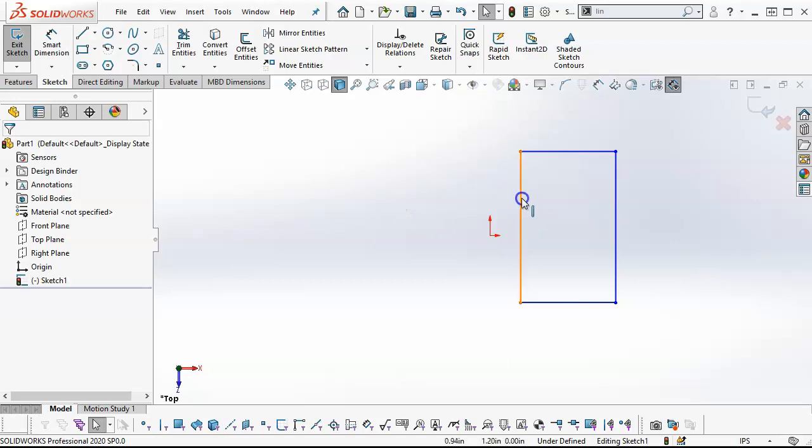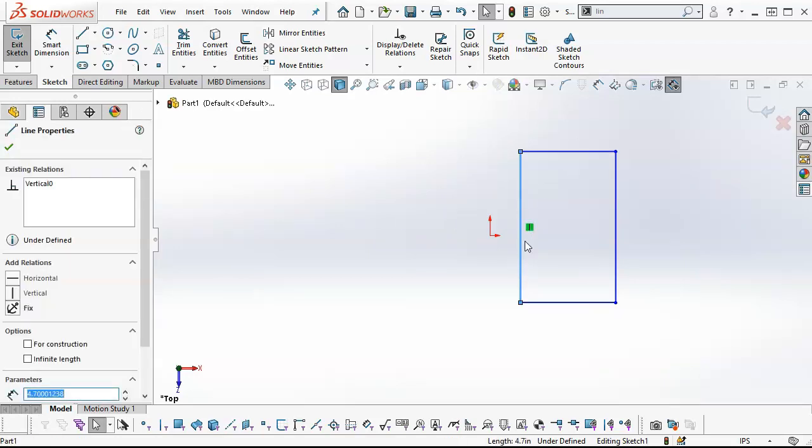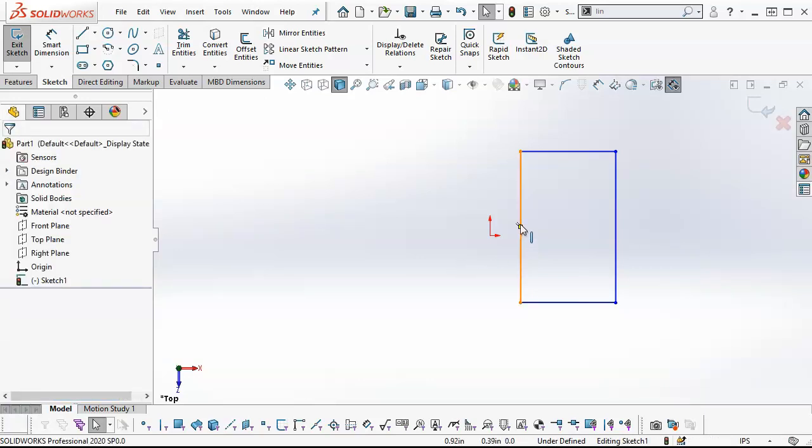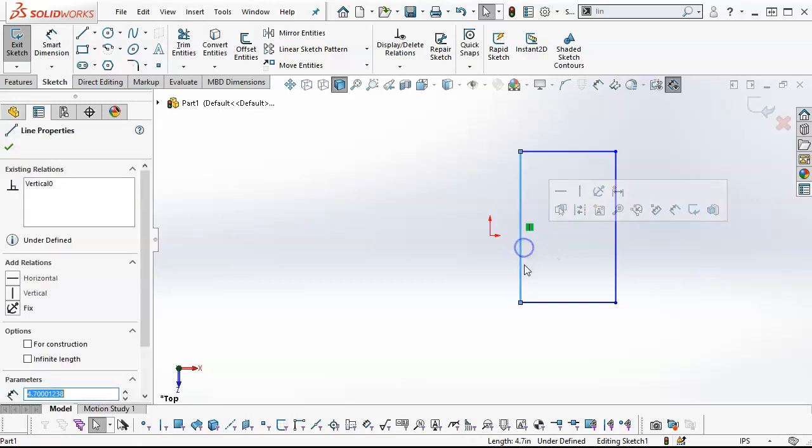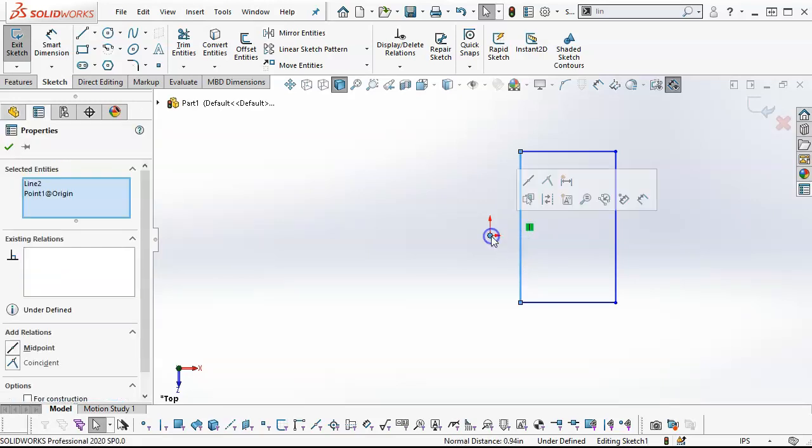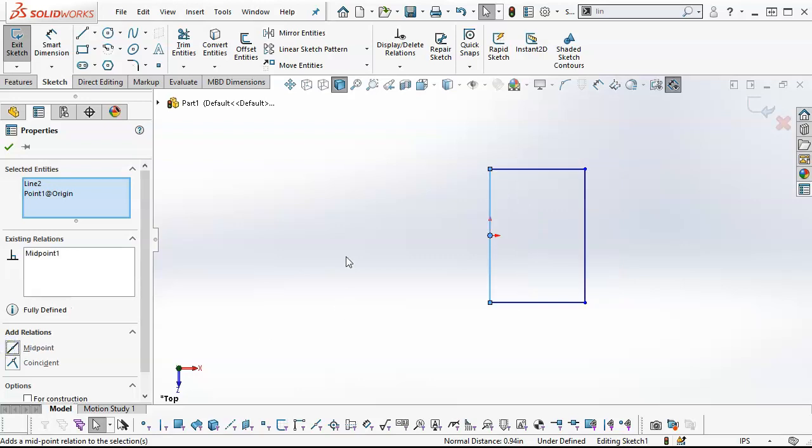The difference is that when I pick on something, it's only showing me the relation for that item. And so as I hovered along in that selection, there's the midpoint. That of course is my endpoints. And depending on the geometry, I'll get different results. So sometimes I need that midpoint. Sometimes it's just going to be on the line. And when we go to Control select the origin, then on the pop-up I'll see midpoint, or I can come over to the left and make it a midpoint.